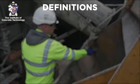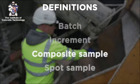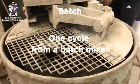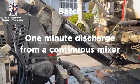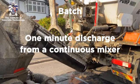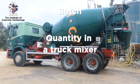The following are important definitions in relation to the sampling of fresh concrete. A batch is the quantity of concrete mixed in one cycle of operations of a batch mixer, or it is the quantity discharged during 1 minute from a continuous mixer, or it is the quantity conveyed ready-mixed in a truck mixer.